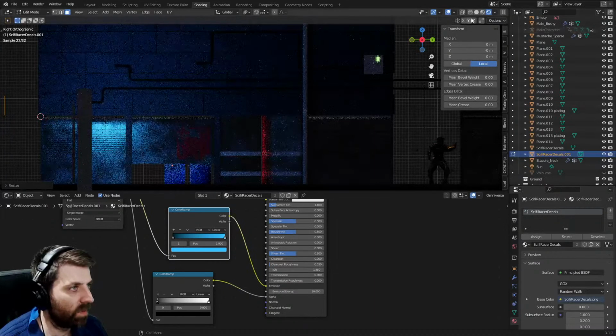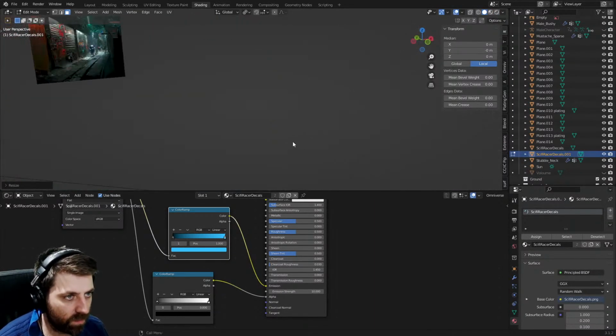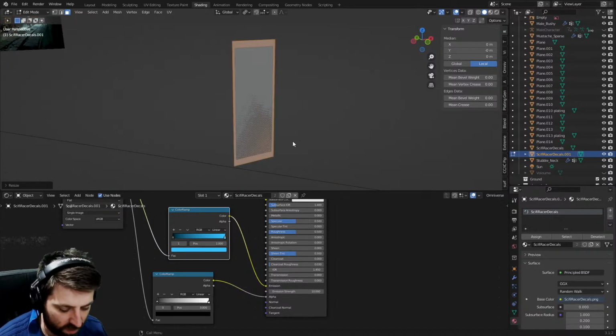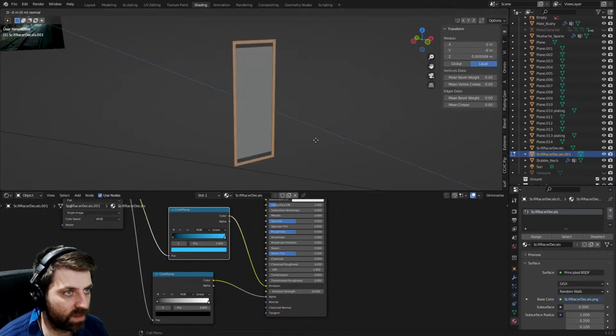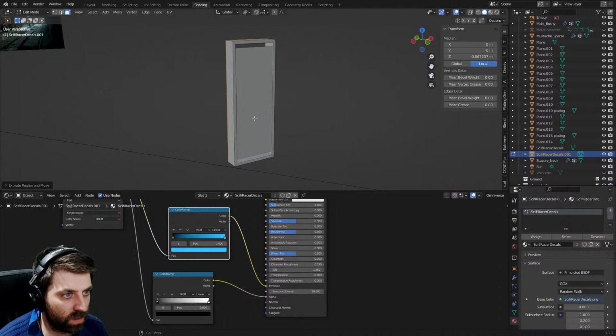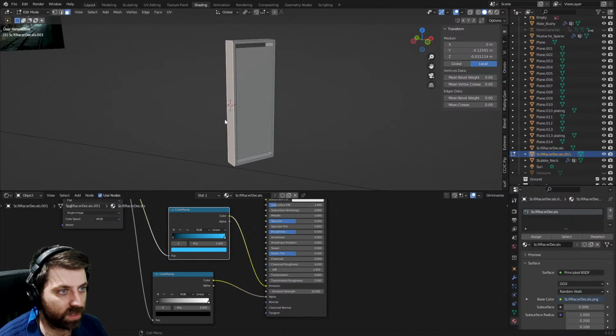Let's go into solid view. Where are you? Here we go. Period key. You can do this, Marco. You've done it 1,000 times before, buddy. I to do an inset. Delete faces. E to extrude. Select this edge. Shift S. Cursor to selected. Let's go back into layout mode.